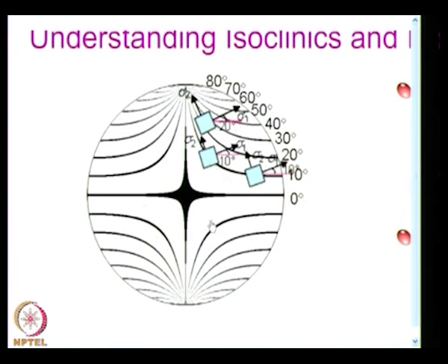You have to extract this data from several different positions of the polarizer analyzer combination. You do not see this information available in one experimental exposure. This is what you have in conventional photoelasticity. That is why people said, can I plot the isoclinic field for every point in the model domain, and digital photoelasticity has now achieved that. You may have to take a few images and process the intensity, and it is possible for you to generate plots of this nature by post processing the data acquired.